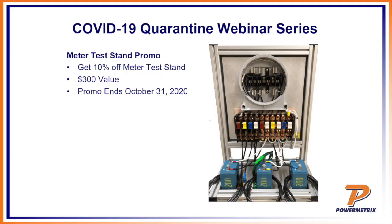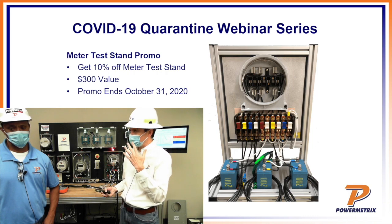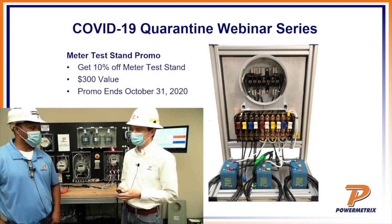The nice thing about this bench is you can test CTs, you can test a meter. It's a really economical bench that the guys can use in their meter shop. Doesn't it have some resistor of some sort? Oh yes, good point. If you have a 3 Series and you ever want to check out the burden measure, it has a built-in resistor on C phase where you can actually simulate resistance, so you can see how that burden measure goes in and out.